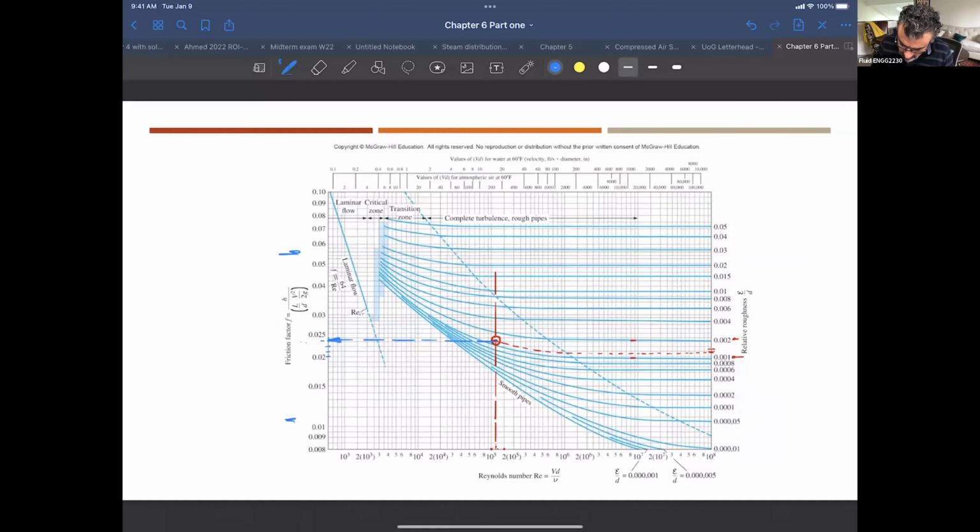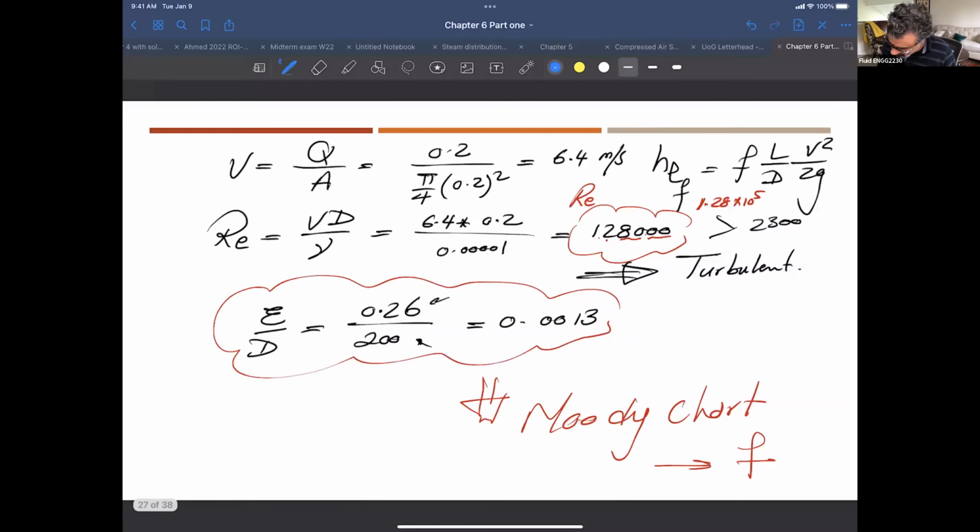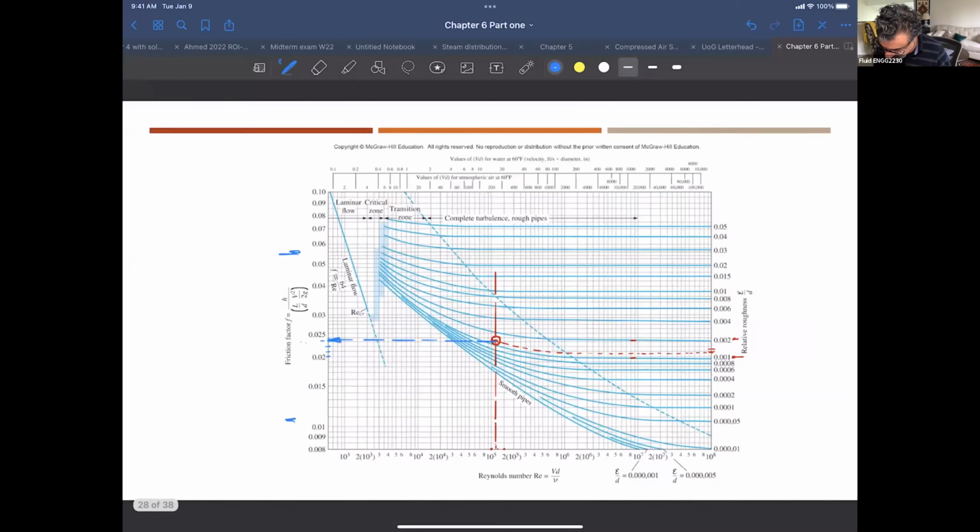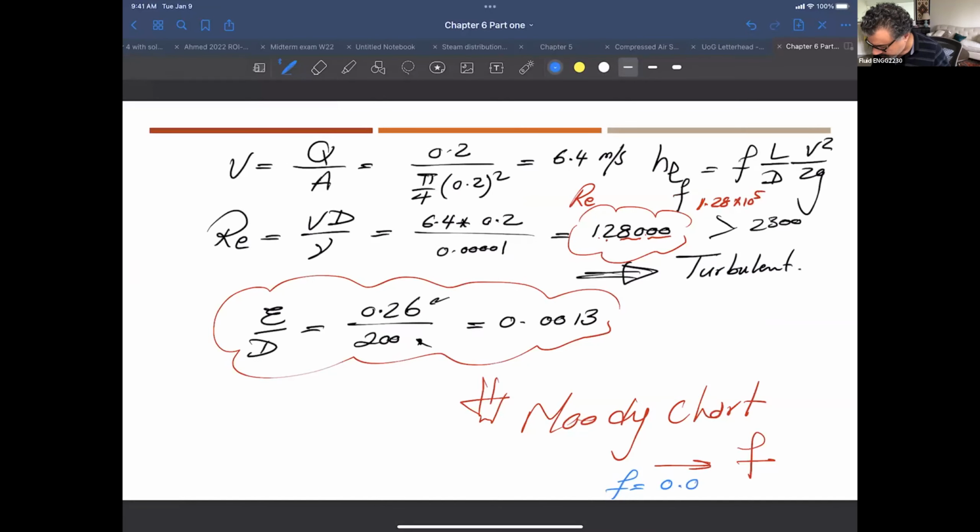So I can actually share with you the values that we are getting here. I get it from the software I have for the friction factors, because all this is in the computer as the Colebrook equation. But there is going to be some tolerance. So if you get 0.0235, for example, something like that. We're not expecting you to be that close, but it's 0.02. It's not like 0.01 or 0.03. It's within the range of 0.02 something.